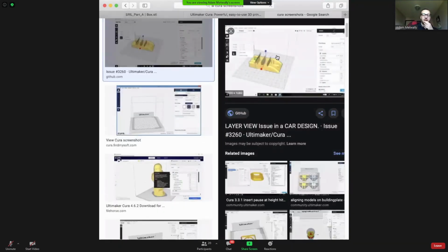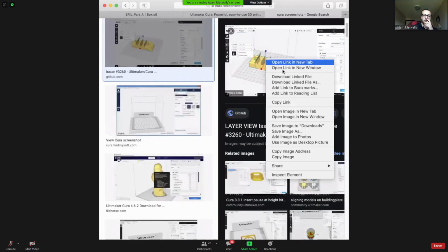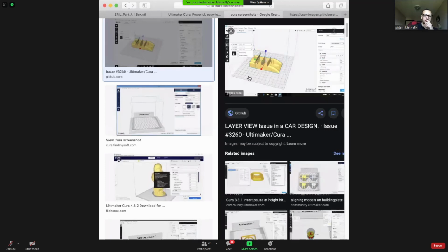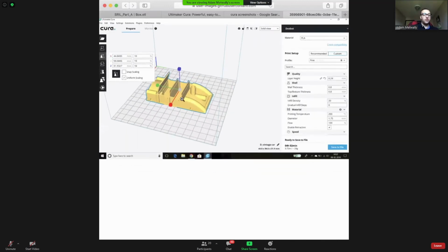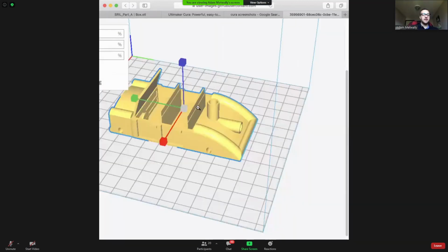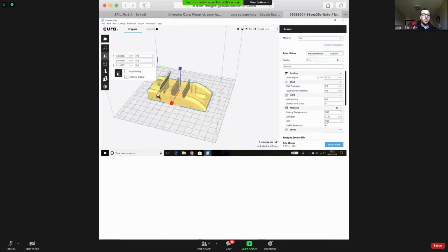So what ends up happening is that it looks something like this, where essentially you see this part within the print space that's actually in your printer. So you can load different printers that'll have different print space. Depending on the printer, you'll be able to tell it what material you're using, whether that's PLA or ABS. Set your layer height, which we kind of talked about.